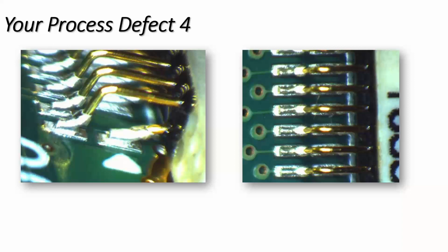So certainly you could look at a solder paste which has got less activity, and that would reduce the amount of solder wick away. But what I would try and do is find a way of balancing the heat into the part. And the ways you can do that is look at a profile.